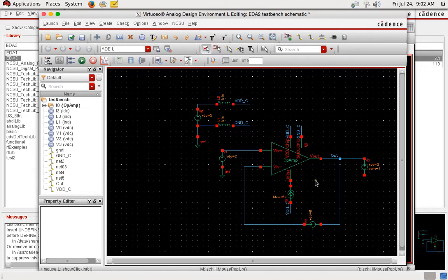Okay, so now we have several choices. You can either insert a real large capacitor to block the DC, or you can consider changing this into a current source, AC current source, and you measure the voltage, right? So the idea is pretty straightforward. You have a voltage source here, then measure the current, divide the voltage by current, that's gonna be the resistance. Does this make sense? In that way, you have to worry about the DC operating point, okay?